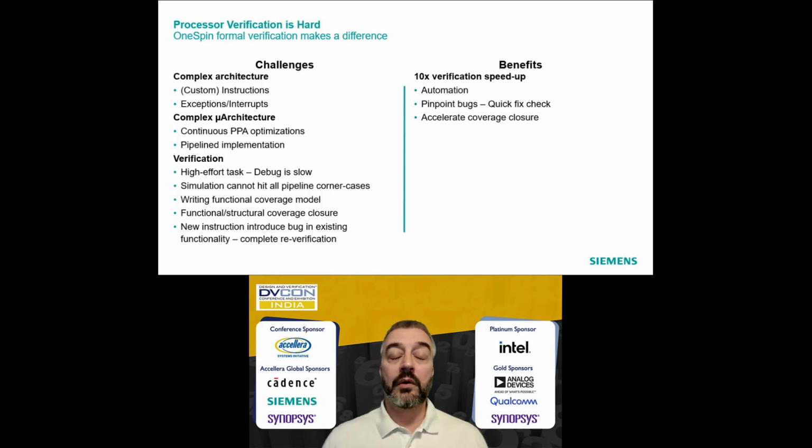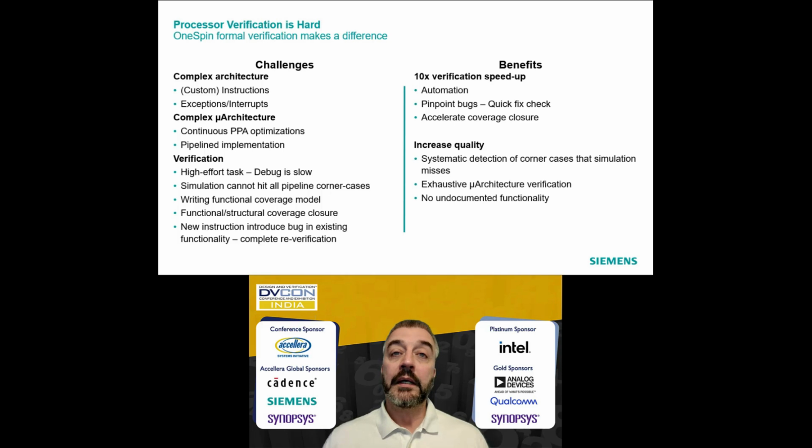So if you can't cover all the integrity corner cases in simulation, have the corresponding formal assertions and export their coverage so that you can get to the coverage closure of the overall project quicker. And also, as you don't really have a major overhead of setting up verification environments on the formal side, you typically also pinpoint bugs earlier, so that overall you do end up with less effort on the verification side and earlier bug reporting times, which of course is also important.